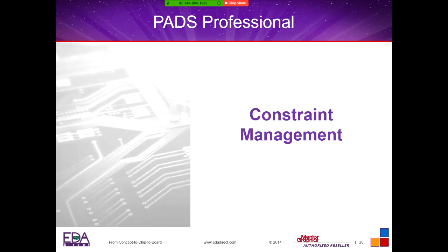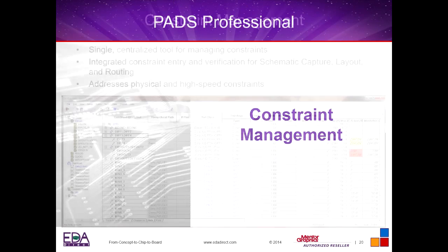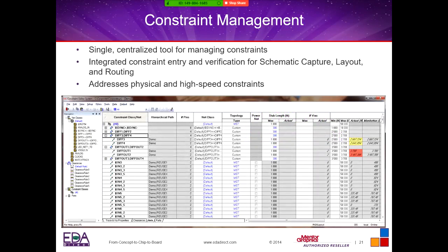Constraint management is going to be a really nice tool that's been added. Before, you were having to go in and do a lot of pull-down menus to add all your constraints, and you weren't able to get them into the schematics. But now with the new PADS Professional, you're going to have a centralized tool that's going to manage all your constraints. This can be done in the schematic as well as the layout tool. And we can back and forward annotate that should we decide to make any changes while we're in the middle of the design.